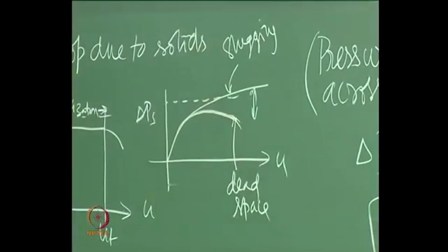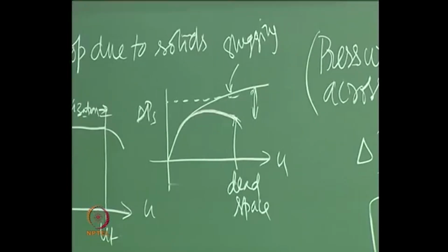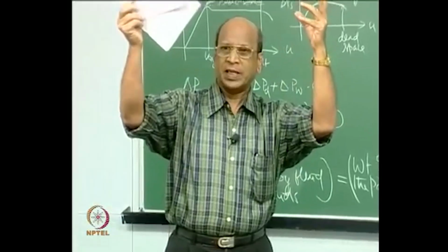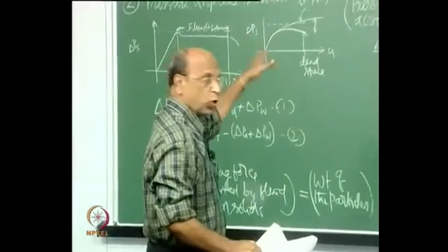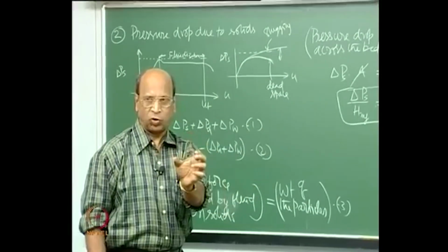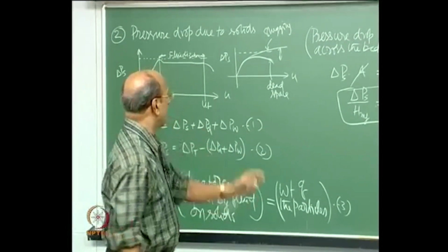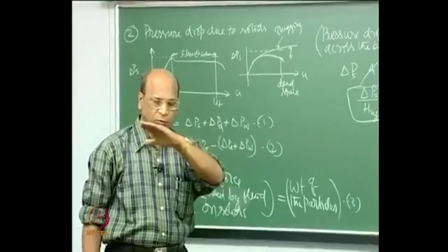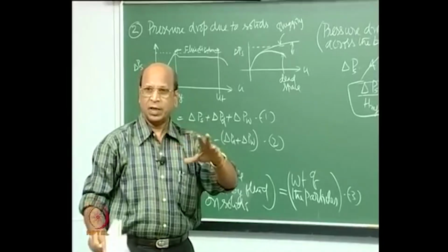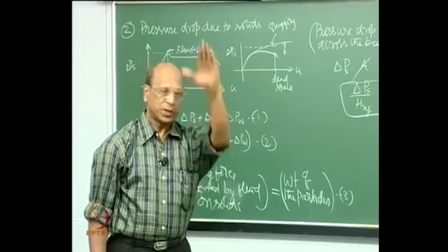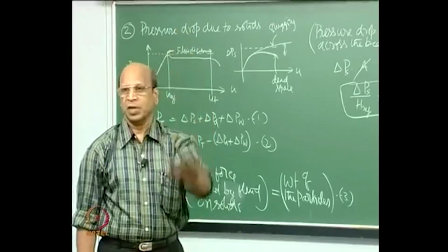What happens during slugging? The entire cross sectional area is occupied by the gas, and the solids above are just pushed up, right. So then the pressure drop may be more there, because the entire thing is just pushed up, and generally in a very narrow cross sectional area. When it goes up, all the solids can be at one point, they cannot be supported, the slug will break and then the entire bed will fall. At that time pressure drop will be fluctuating up and down.